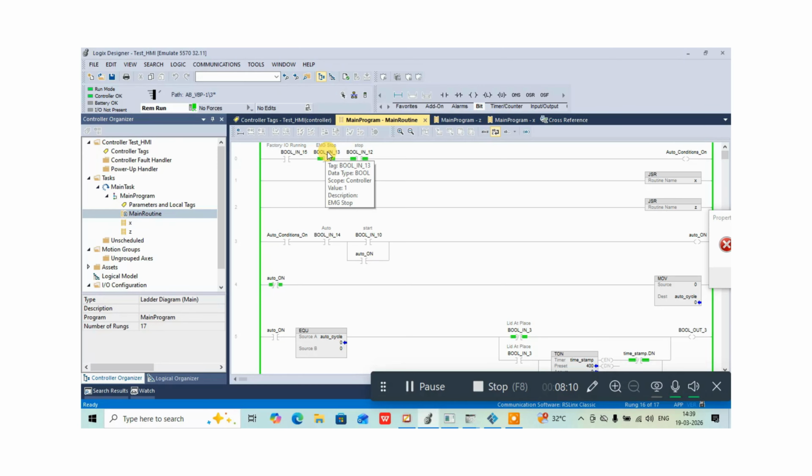Why are the emergency switch and stop buttons given as NC buttons? Did you know? I will explain about it. If the emergency button or stop button is given as a NO button, and anything goes wrong with the wires or buttons, what will happen?